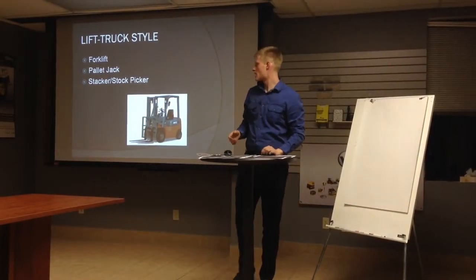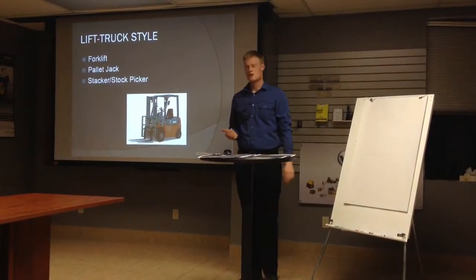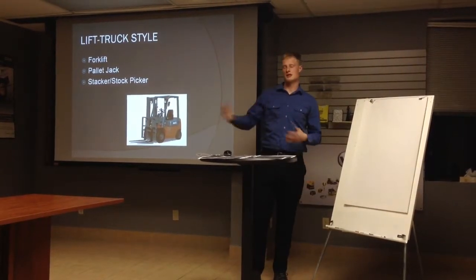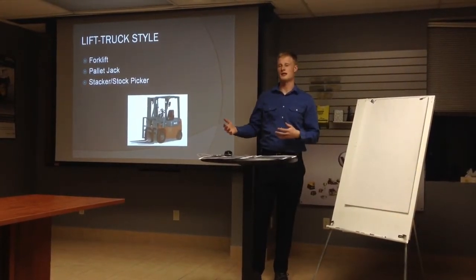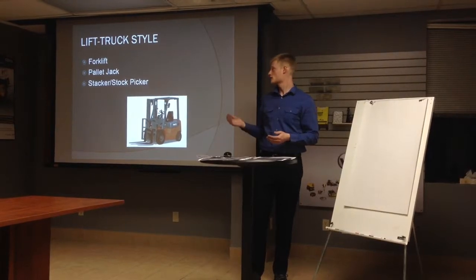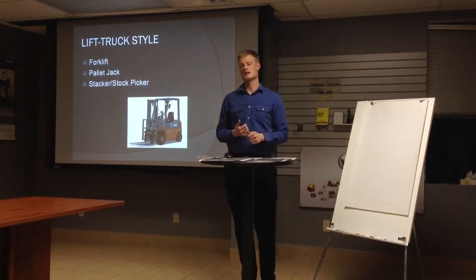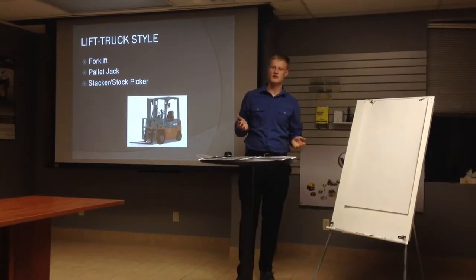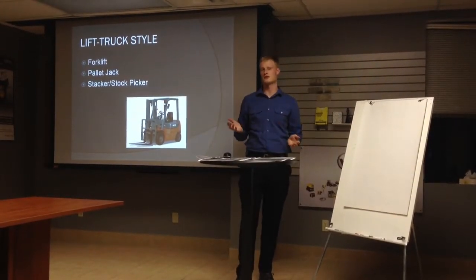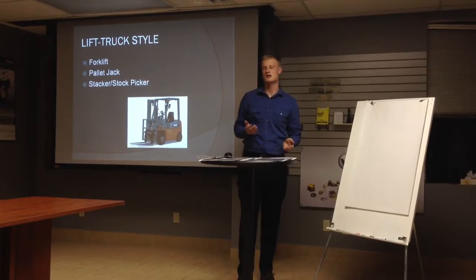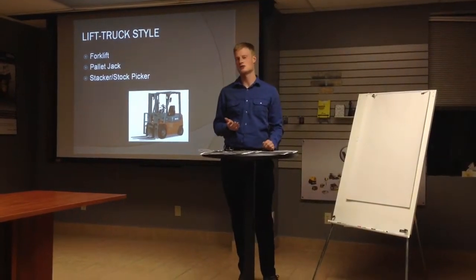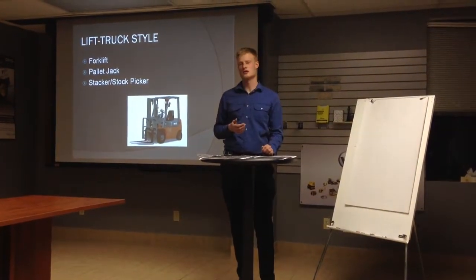We have lift truck styles. Of course, what style of truck is going to be used is dependent upon the product style, again. With regards to the lift trucks, there's many different things to think about again. The capacity. If you have a 12,000 pound lift truck lifting skids of 4,000 pound material, then you have to consider the weight capacity of the actual leveler when thinking about lift trucks.